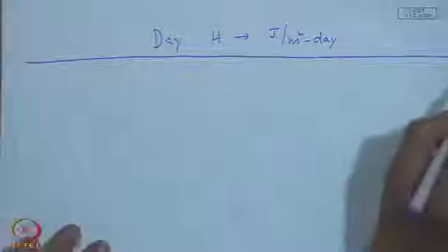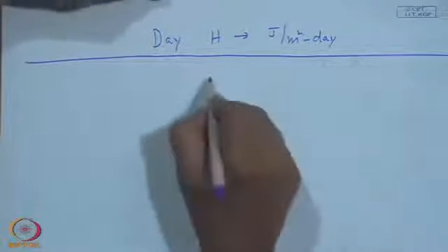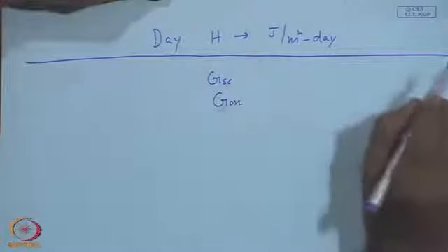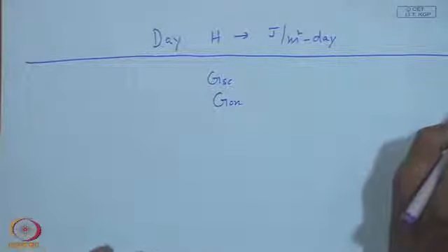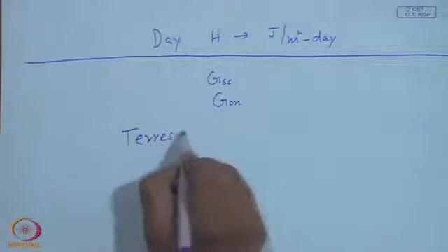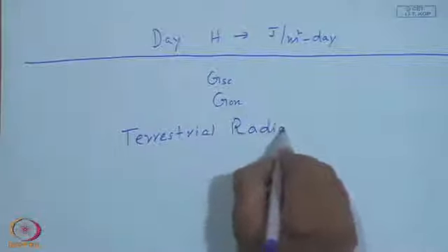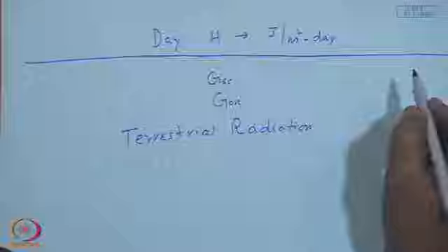Now, we have considered the extraterrestrial radiation by first defining the solar constant, and then on a normal surface which takes into account the distance variation between the sun and the earth. Now, we try to come down to earth and call it terrestrial radiation. In the process of transmission through atmosphere, part of the solar energy is absorbed by CO2, water molecules.